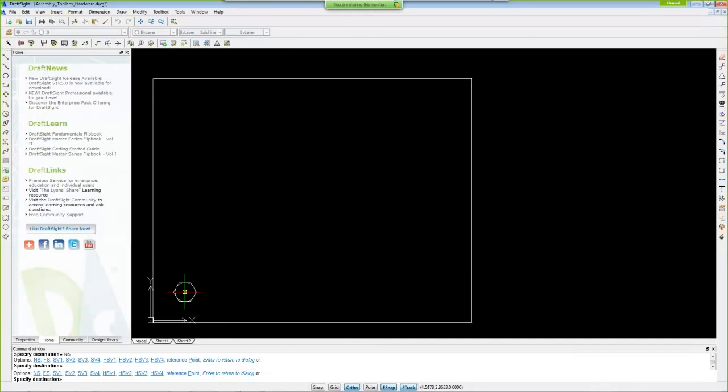All right, so now I just find a spot. Don't forget, tracker's still on, so I have to click 2 spots. Click and a click. Click, click, click, click. And just for fun, I'm going to turn my ortho off on this one and move the screw into a position that's a little off kilter, just to show you that you can do that. So now I've added those bolts to the top view by just a right click of the button.